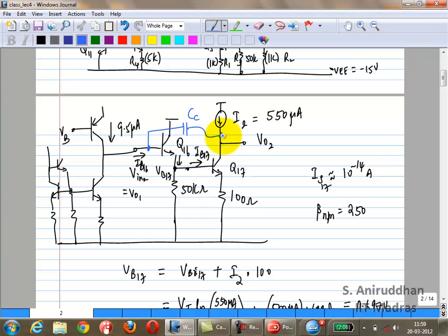But one thing we have not studied is differential op-amps, that is, when you have differential inputs and differential outputs. There are some special things you have to take care of. The basic structure will be very similar. What is the difference between having a differential output and a single-ended output? Actually nothing much. Instead of having a current mirror there, you would just put in two current sources. Now that you have a differential case, you need to make sure that the common mode voltages are the same on both the outputs, because you want a purely differential output. So the two sides need to be completely symmetric now for DC and AC.